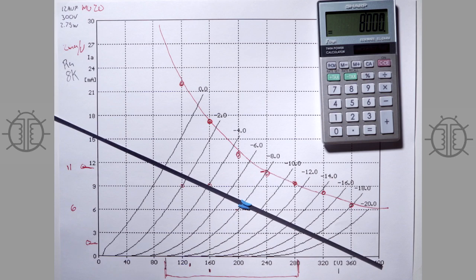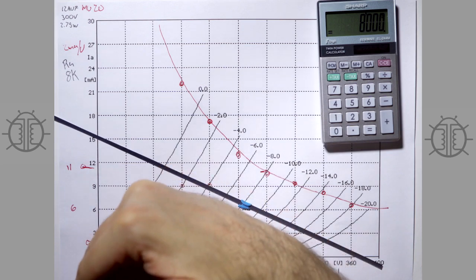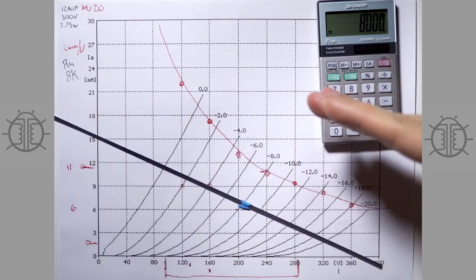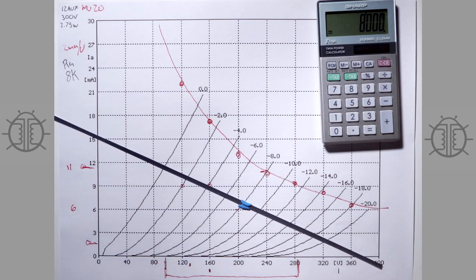Regulators do a good job over a limited range of approximating them, voltage regulators. And then the current source is the opposite. So the current source would have an infinite output impedance and would supply the same amount of current into any load. And all of the lines here, the grid lines, would be straight across like this. And it wouldn't have a voltage gain so much anymore as it would have a pure transconductance.